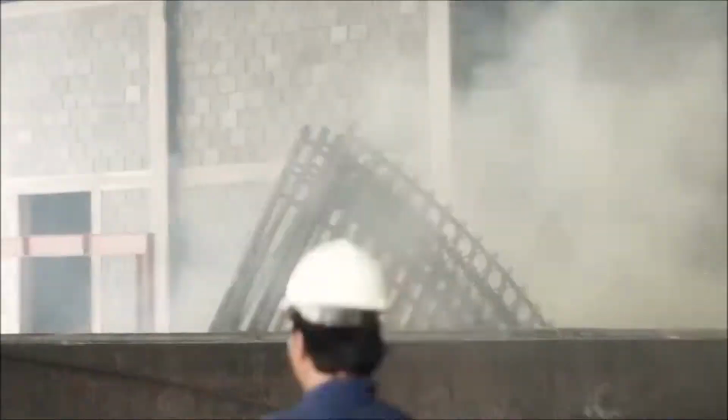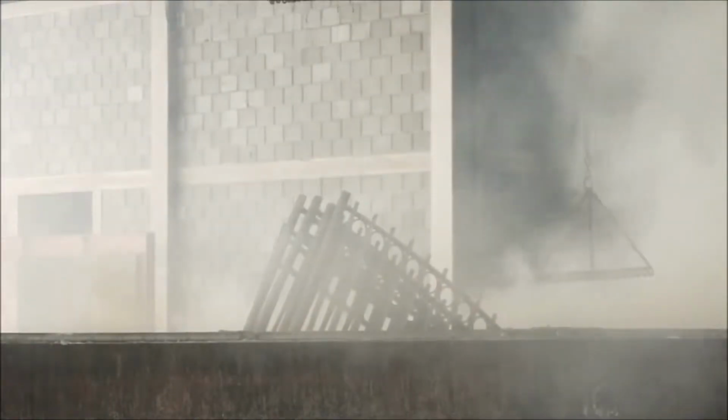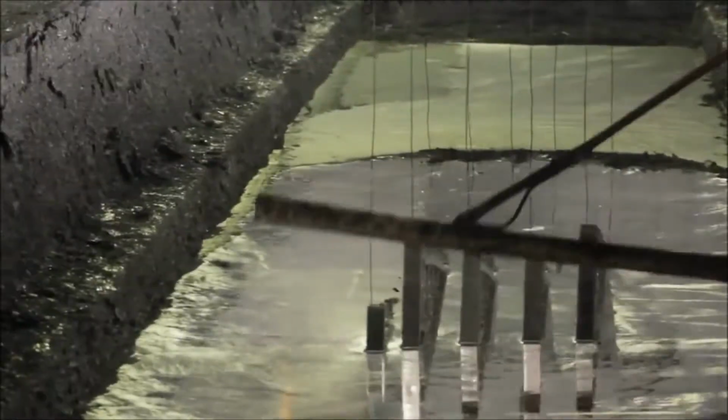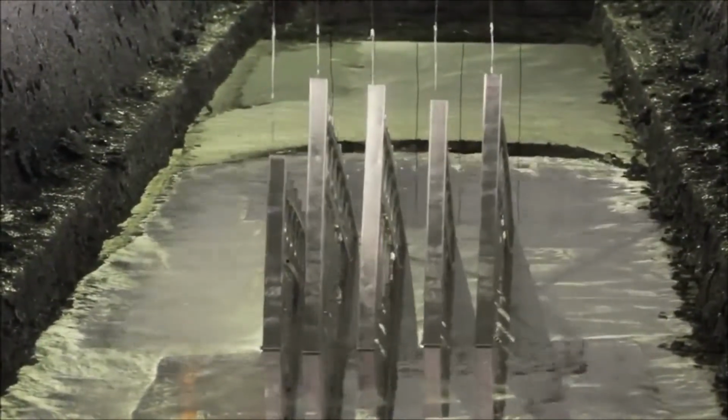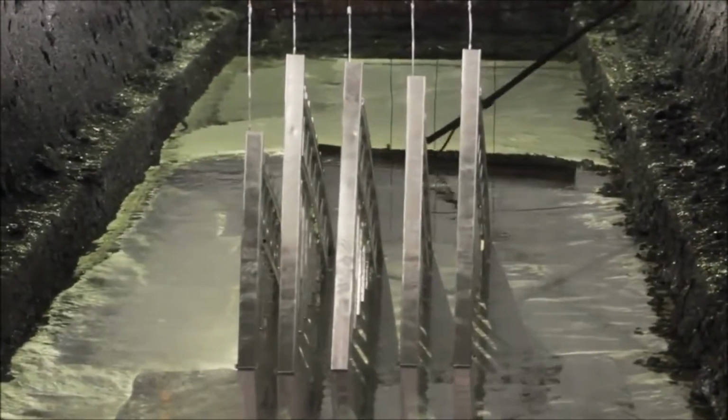The molten zinc is about 450 degrees Celsius. It's 1,000 degrees Fahrenheit. Yes, around about, give or take. And as you can see, the way the gates are hung on the hanging jigs, they're hung on an angle. So as they slowly take out the product from the molten zinc, it allows the molten zinc to come off freely, so that it doesn't have any large blobs. So it tries to give it the smoothest finish that we can.